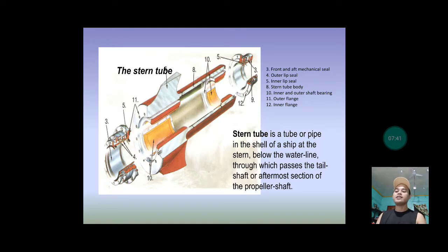So the higher the gravity tank, the higher the pressure of your sealing oil. That seal oil will counteract the pressure of the seawater level outside of the ship.